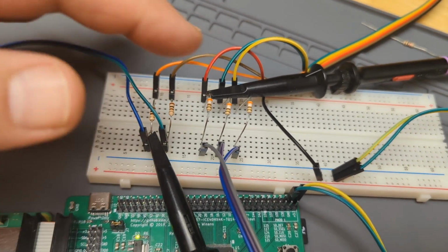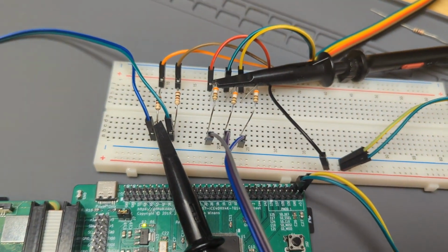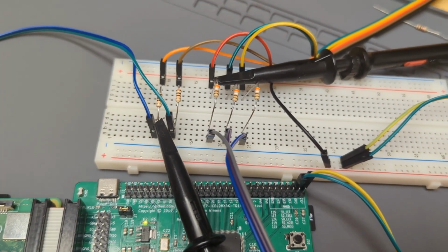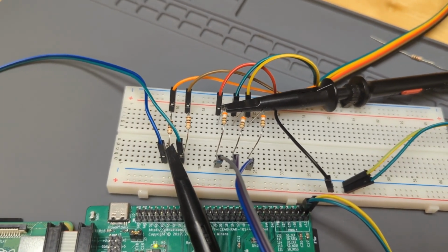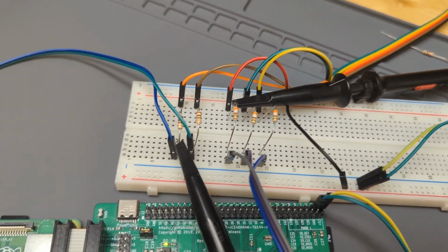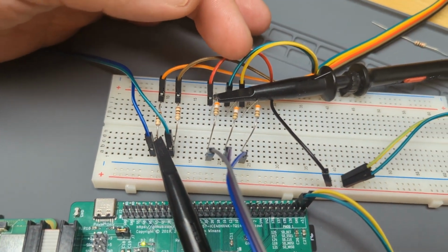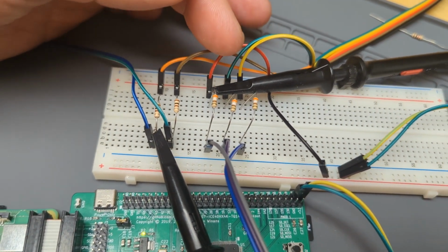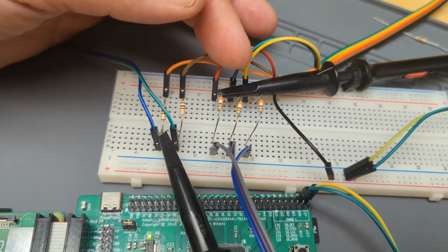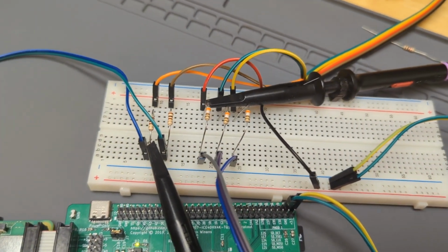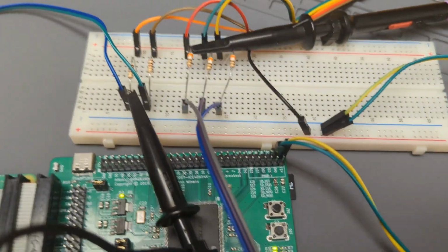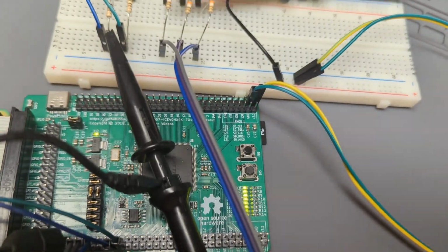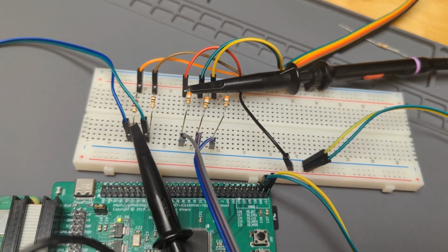So these are 390. You're probably better off with a 330 or a 360 to get the right amount of voltage on the screen, which is 0.7 volts over here if you want white. My screen, I notice, is a little dark, but that's okay. I don't care. It's white enough. It's a very light gray, and it's doing what it's supposed to do, and I'm not overtaxing my FPGA. So that is the goal, of course.